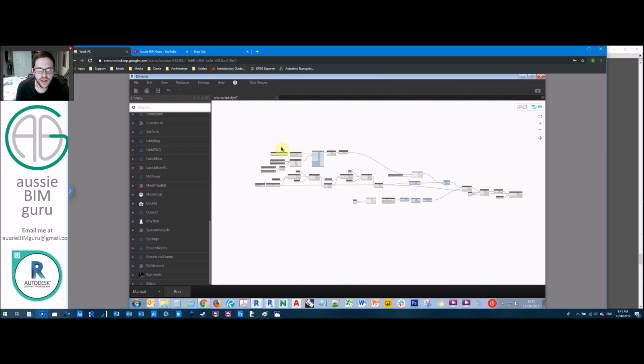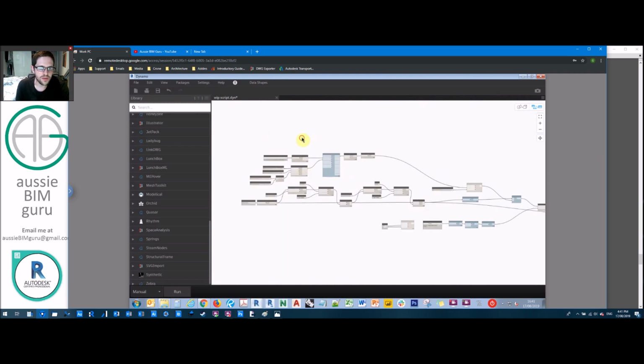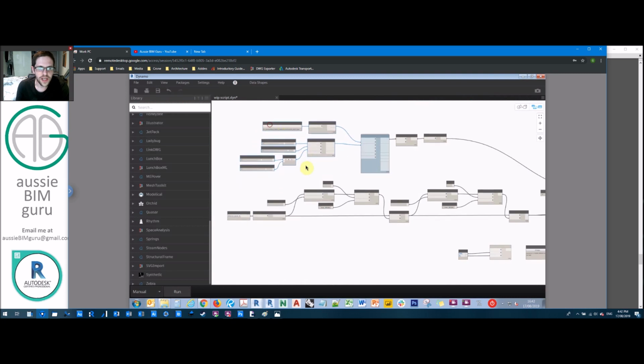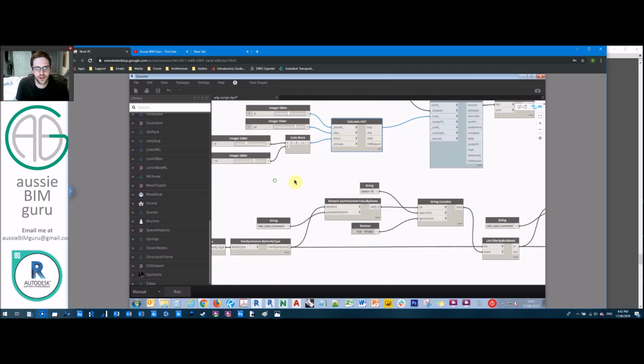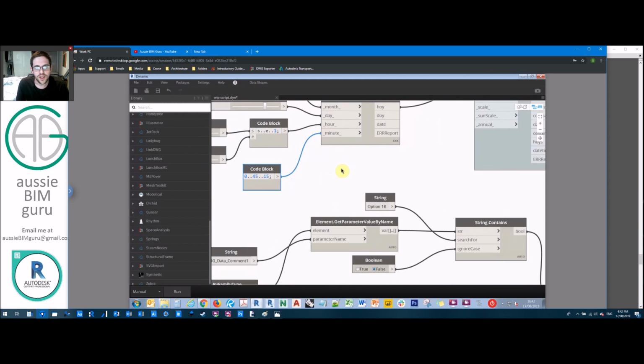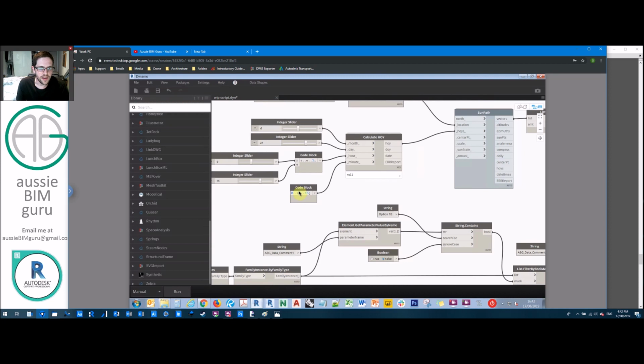which you probably recall if you see it, I won't explain how it all works now because hopefully you've seen the last part. So the first thing we need to do to change our script is introduce the minutes factor to our range. What we need for that is just a range between 0 and 45 with a step of 15, which will give us 0, 15, 30, and 45. Because we also want to introduce the increments of 15 minutes to our time range, because we're testing every 15 minutes now. It's really important to note that this needs to be a cross product in its lacing in order to generate all the possible times between the mix of the hour range, the day, and the minute range.